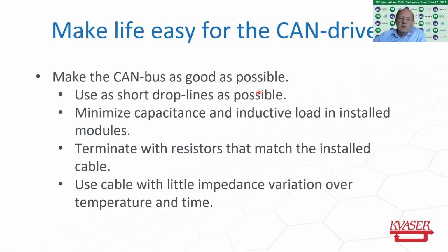In some cases, you need to have drop lines for proper cabling, because of weight or location constraints, and you cannot run the cable wiring back and forth to reach all the ECUs. So sometimes you have to have drop lines, but at least you should make them as short as possible to minimize the reflection you get when the signal reaches the drop line.